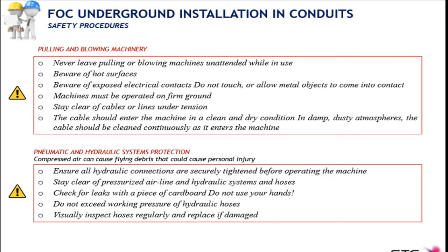Specifically on the pneumatic and hydraulic systems that are used for blowing, compressors and so on. They are carrying important pressure forces in the hoses and pipes. So pay attention to these points and make sure that the hoses are properly clamped and fixed onto their equipment.